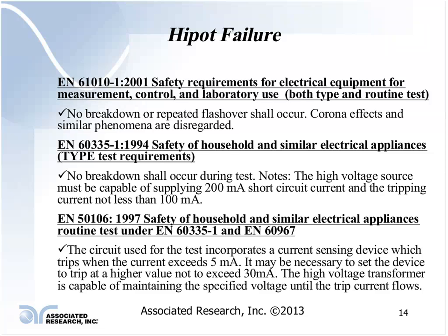As a type test, I don't have too much of a problem with using a high current source. I've got more of a problem using it on a production line, and typically that's just due to training of the operators. You've got to remember, whenever you're doing a high voltage test, you are applying a high potential, thousands of volts in some cases, to a product's insulation.